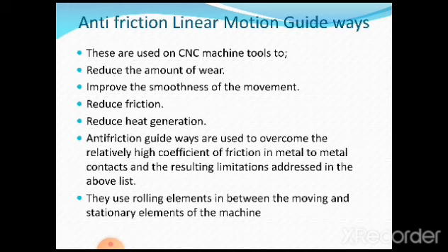A linear ball bush uses recirculating balls within a bush type of bearing. These are designed to run along precision ground shafts for frictionless movement over varying stroke lengths with high linear precision. That means it is possible to achieve more movement of the work table with a high accuracy of positioning, because whenever we carry out any machining operation, especially on CNC machines, there is a continuous change of the position of the cutting tool as well as the workpiece being held.